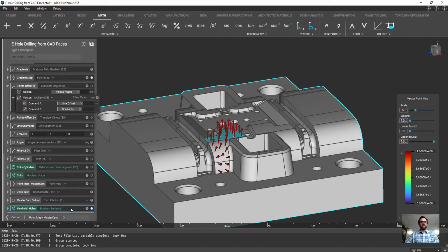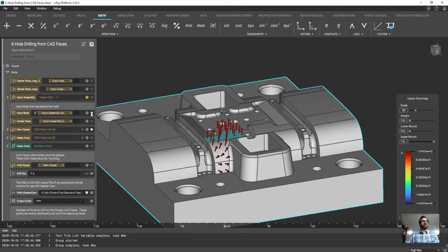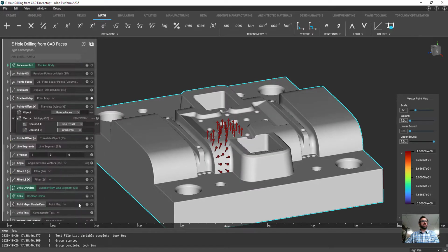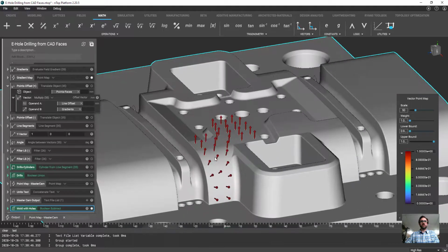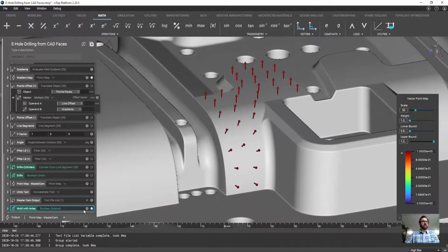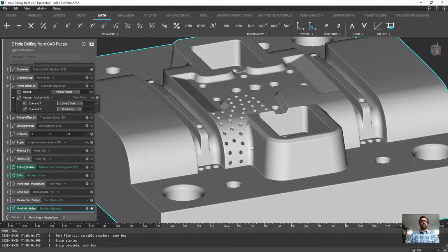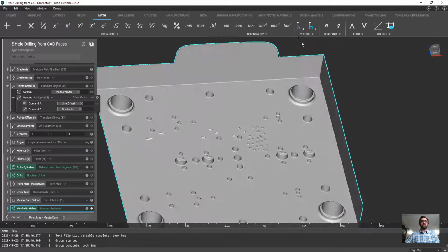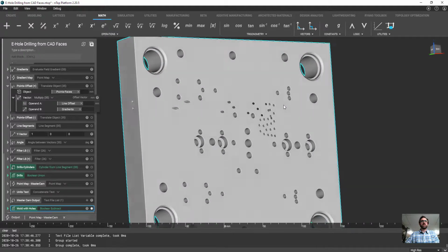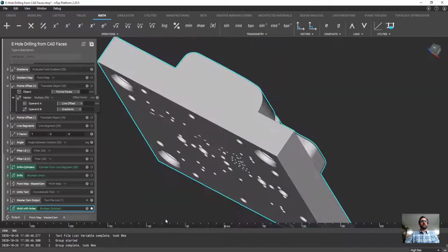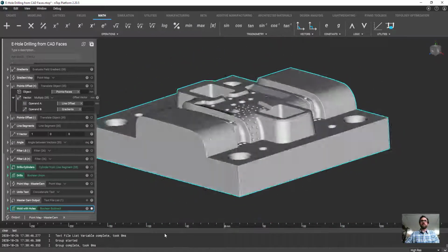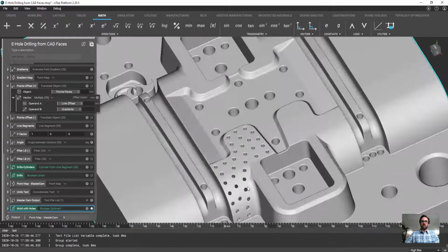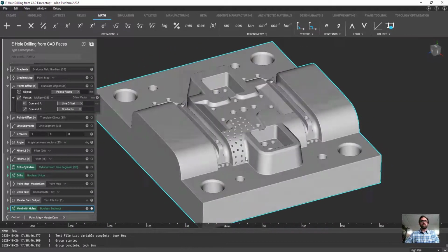And in this scenario now, if I turn off my original CAD file, we can now see the implicit with the holes inside of it here. So I'll isolate that. And now you can see how those objects. So now that same operation actually pierces all the way through the object here because of our long line segments, and then is completely normal to the surface. Pretty cool that we can be able to do this in nTop.